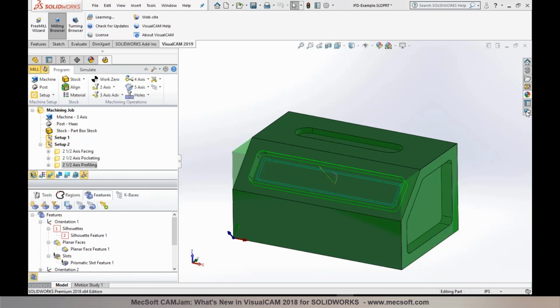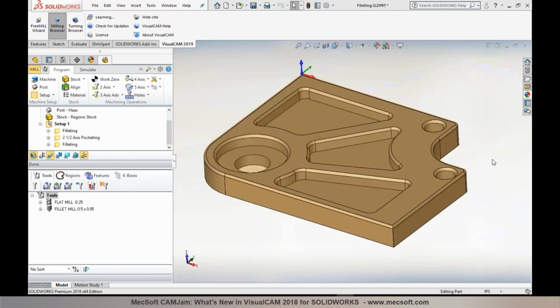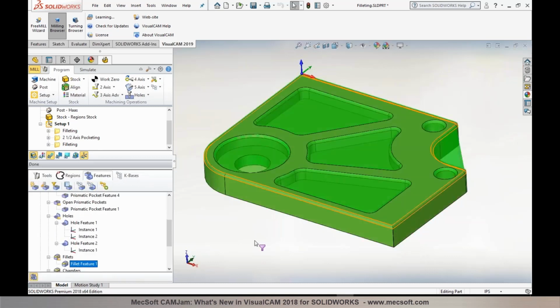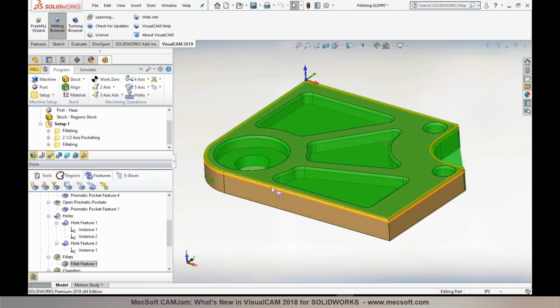All right, the next thing I would like to cover is a brand new method that we've added in 2-axis or 2.5-axis machining, and this method is called fillet machining. It is available in all our configurations starting with standard, so any configuration standard or above will include fillet machining. We talked about the detection of fillet features in feature detection machining, so you can identify fillet features using feature detection. As you run a feature detection, it automatically identifies the fillet features on a part. You can right-click and choose filleting, and it automatically programs a filleting operation.